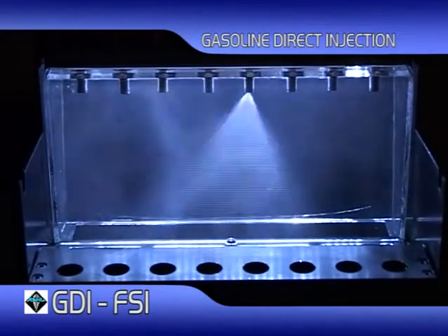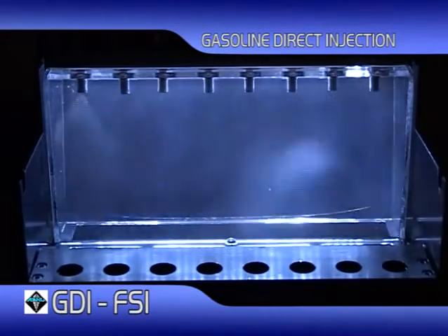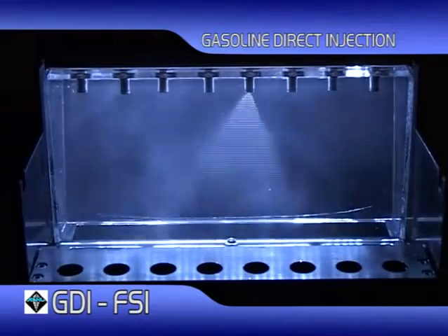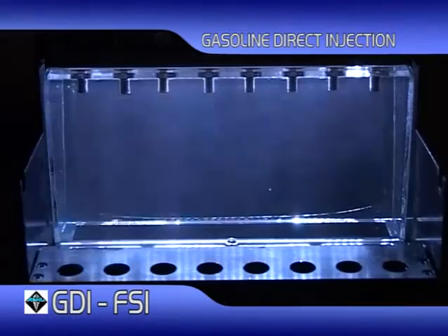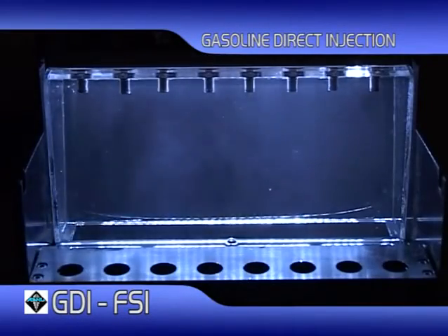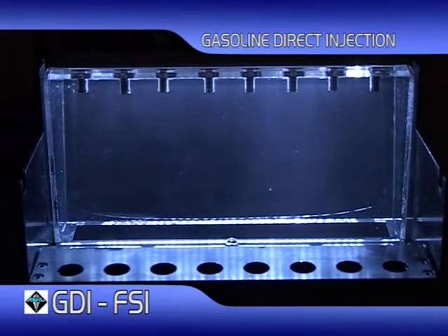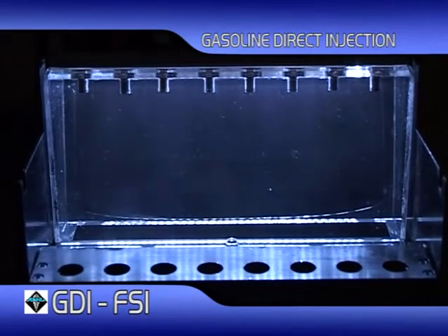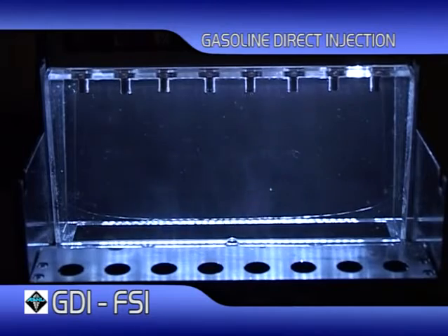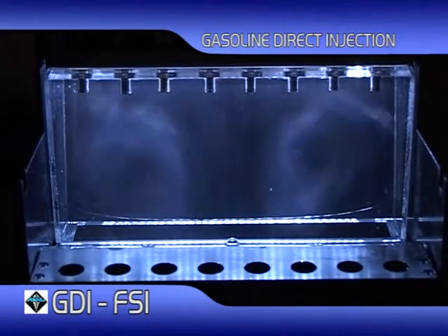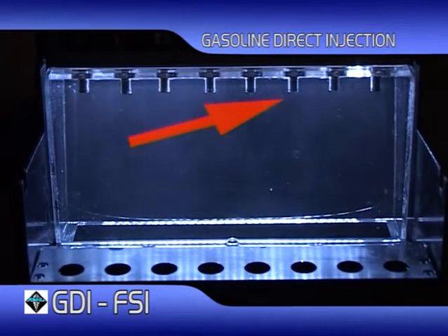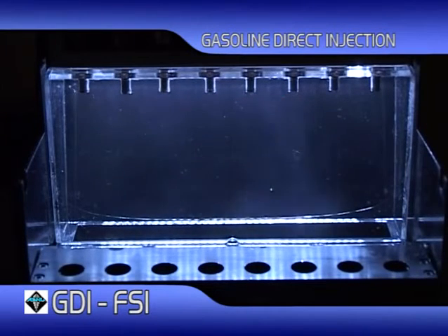Here we can see the injectors operating in an exaggerated mode. This allows the user to examine and compare the injector's spray pattern for consistency of fuel distribution and atomization. Using the up and down keys, we can select individual injectors in turn. While examining the spray pattern, we are also taking notice of the amount of atomized fuel created by the injectors and making a mental note of the differences between them. In this clip, we can see that injector number 6 has a much weaker spray than the previous injectors and releases a lot less atomized fuel.